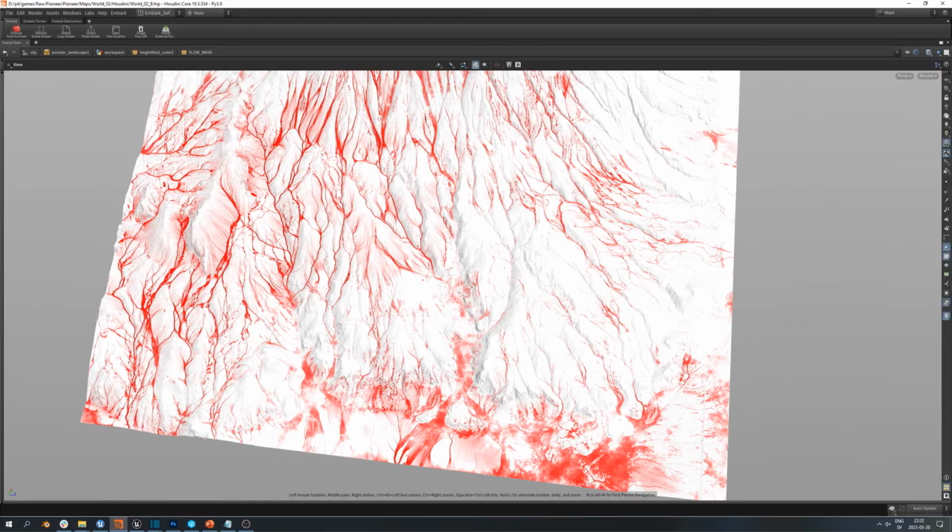So we needed to get nice looking deformation, and even more importantly, different masks like erosion flow and sediment deposits for our in-game landscape material masks. We will mostly rely on real-world data, but there will be cases where we need to fill the gaps with procedural solutions, and having a bridge to Gaia in Houdini fills that gap. For the masking part, we're using standard Houdini height field masking nodes, which offer a great range of feature-based options. To supplement that, we also add some flow maps from Gaia. Using the erosion in Gaia with a very short duration will give you these nice-looking thin flow lines.